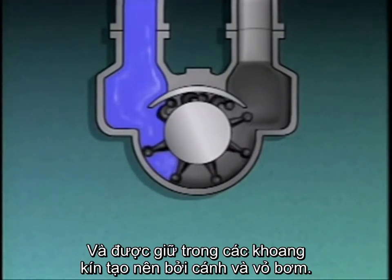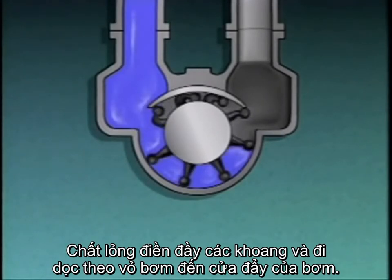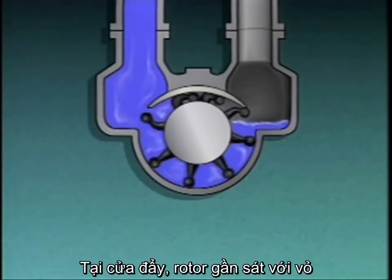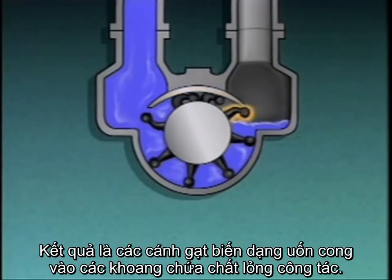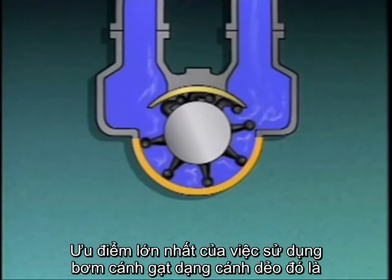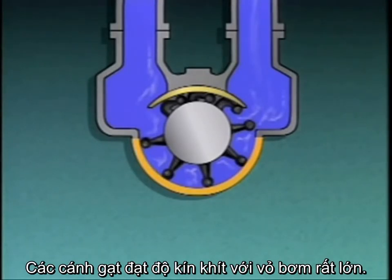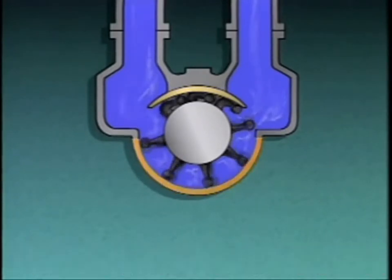When the pump operates, process liquid is drawn in from the suction of the pump and trapped between the moving vanes and the casing. The liquid-filled spaces are moved along until they reach the discharge of the pump. At the discharge, the rotor is closer to the casing, so the pumping area is narrower. As a result, the vanes flex by bending over into the spaces containing the process liquid. This makes the spaces smaller and forces the liquid out of the pump. The big advantage of using a flexible vane pump is that the vanes form a tight seal with the casing. This characteristic is often used in pumps that are required to draw a vacuum on a process.